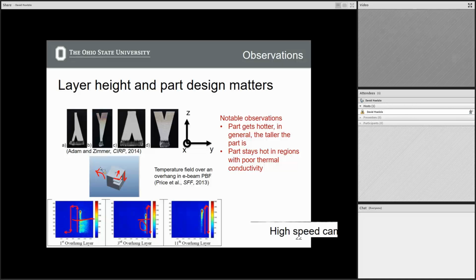Yeah, we'll actually get into that a little bit. There definitely is heat dissipation into the surrounding powder, and E-beam is going to be better because you get these little necks forming between the powders. Laser processes are going to be quite bad, with less than 1% in terms of conductivity of the unfused powder compared to fused metal. We'll get into what people have experimentally found in the literature in terms of the conductivities of powder versus the actual metal itself.